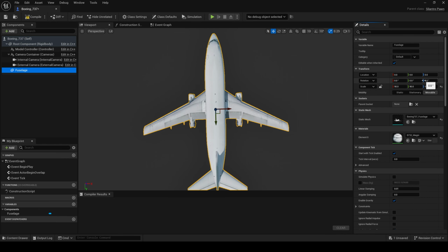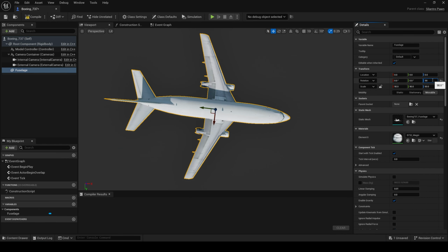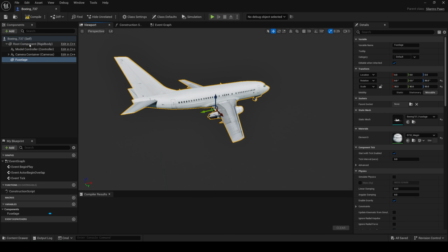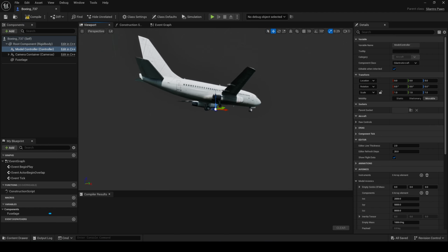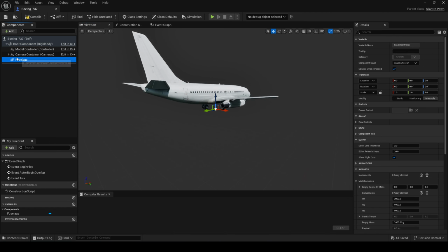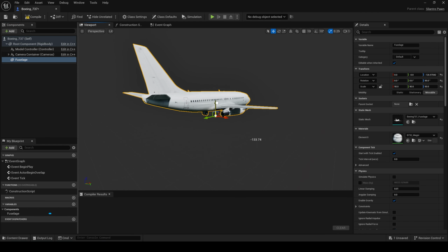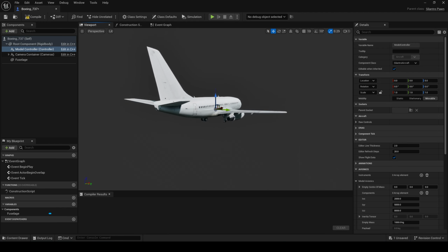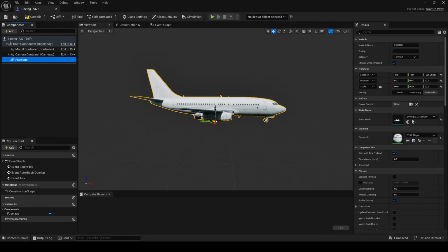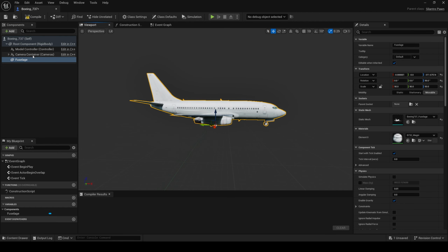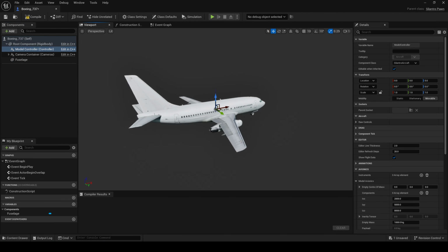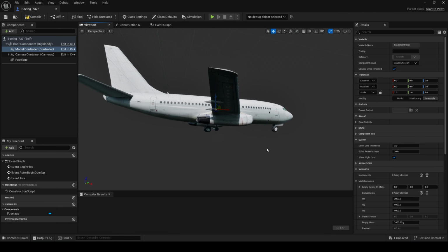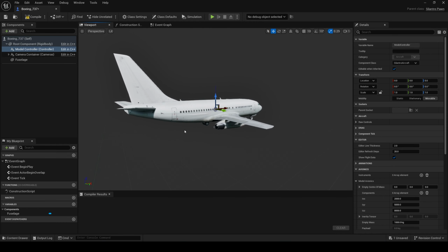So it needs to rotate to the left by 90 degrees so that the forward axis of the aircraft, the nose of the aircraft, is pointing along the aircraft forward direction. Then I also want to move this down a bit so that the center of the controller is roughly at the center of the mesh. This is not a requirement, this is just going to make it easier to configure the center of gravity and all the other aircraft transform components. Then yeah, I think this is perfect.